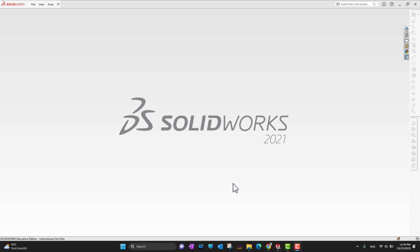So this is pretty similar to Extruded Boss or Base, but it is a bit different. Let's go into this feature and see how it works, because in this feature we just need to select the axis of revolution. In this way it is different from Extruded Boss or Base. So let's go into SolidWorks and see how it works.